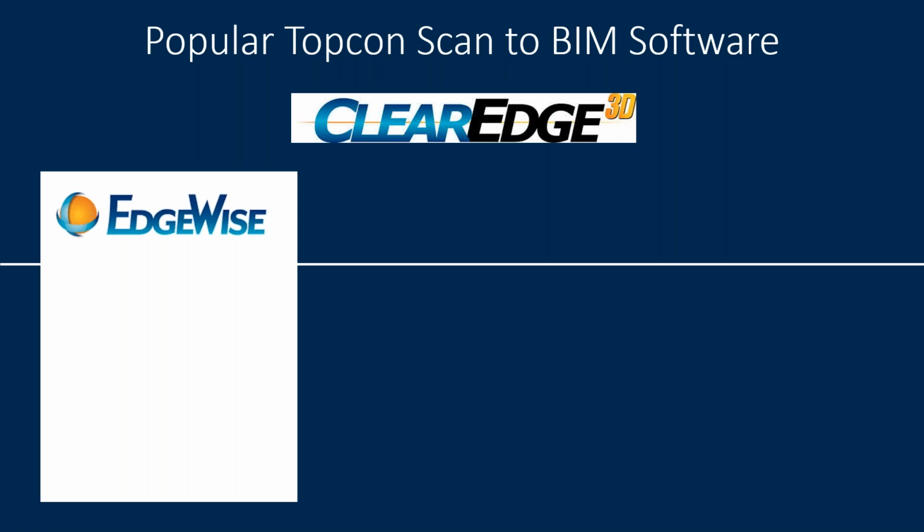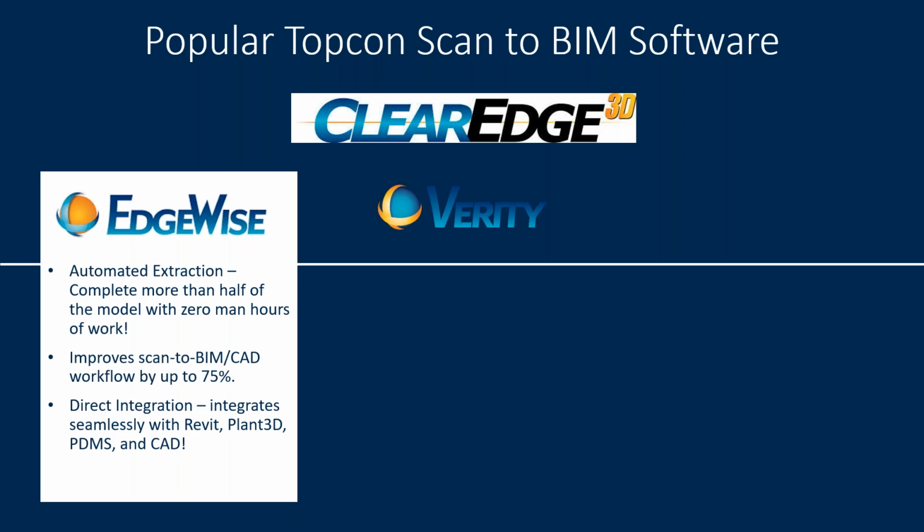Edgewise, if you've joined my initial webinar, you should know what this does already, where it extracts the CAD from a point cloud. So let me say this again. Normally, when you do a 3D scan, you get millions of dots that come in. That's called a point cloud. But you would still have to model the CAD elements of it, and this is predominantly manual still, where, if I could use an analogy, you connect the dots to create a model. It's like opening a coloring book and connecting the dots to form a picture. A point cloud provides you with that functionality, but it can be very overwhelming and cumbersome depending on your knowledge of it, as well as how you manage the data to draw.